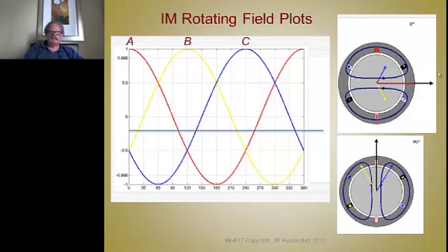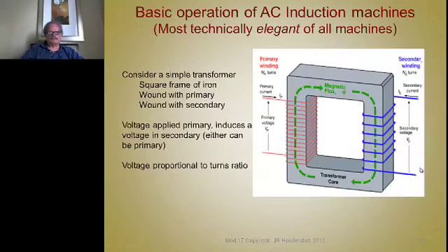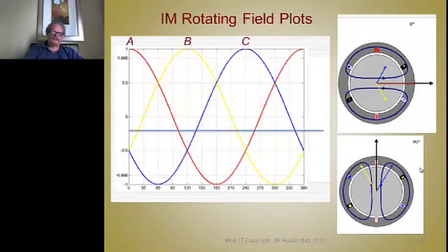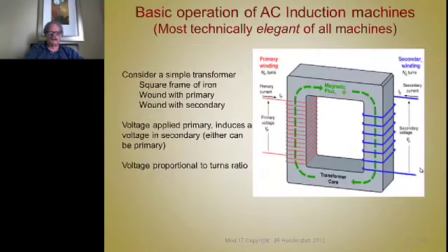And at 0 degrees they look like that. 90 degrees away they look like that. And to control them, we can't deal with them. We have to use transformations to transform these currents into D and Q axis coordinates so that we can control the machine the same way a brushless motor is controlled today. So you have to transform 3 vectors into 2 vectors.